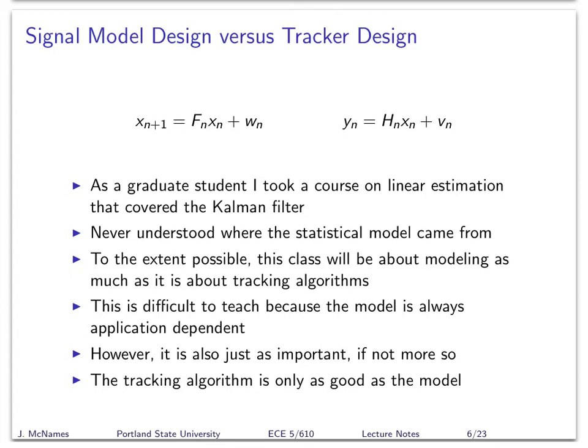And then just a little bit about my background. I think I may have already made a lot of these points as well. In doing model-based signal processing, and in this case I'm showing a slight variation of what we had earlier. Rather than having nonlinear equations, we've got linear equations in this case. And this is what the Kalman filter was designed for. It's the case where there's a linear relationship between what you can measure and your state variable with additive noise, and that your state evolves over time based on some linear transformation of the state variables plus some additive noise.